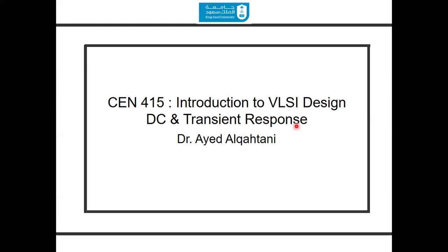This is the Introduction to VLSI Design class, and we will discuss DC and transient response today. Last video, we discussed the transistor theory, which is basically the relation between the current and the voltage in the channel. We had VDS on the x-axis, and we wanted to find the IDS on the y-axis. And we came up with the Shockley model, which has three different regions: the cutoff region, the linear region, and the saturation region.